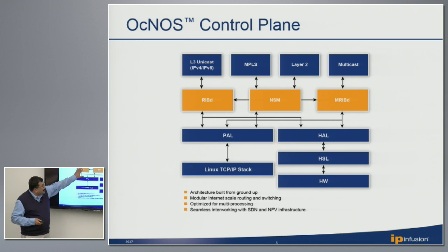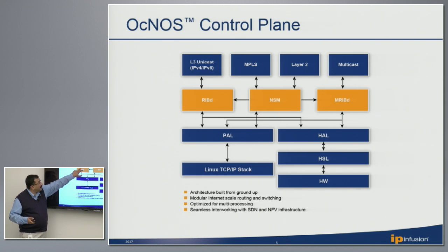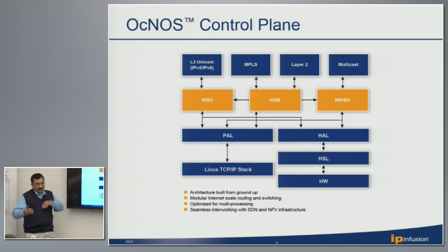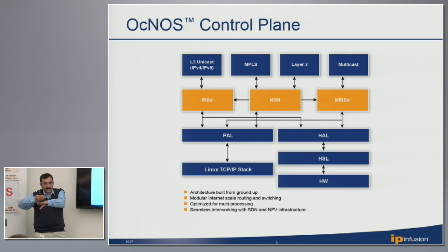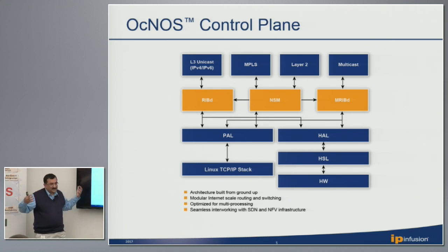And the beauty of this architecture is it can run on any modern processor. It can leverage this because it uses standard Unix domain sockets. So essentially, you can split it across process level, or you can run parts of the protocol spread across. Something could be running very close to the hardware. Like for instance, if you take BFD, things that need to run very close to the hardware will sit right next to a coprocessor or an inline function within the chipset itself. And the rest of the control plane pieces could run in your CPU. So essentially, it gives you that scalability.